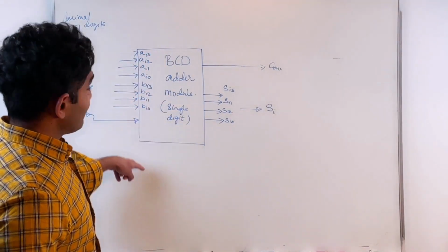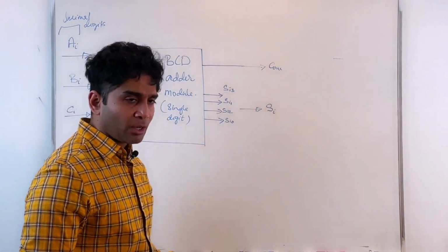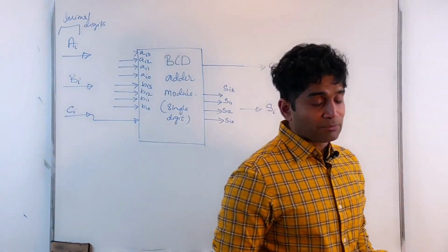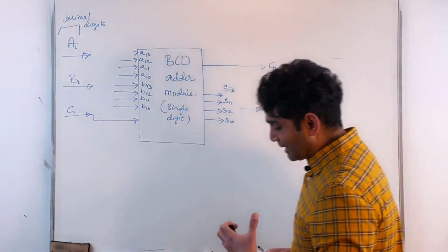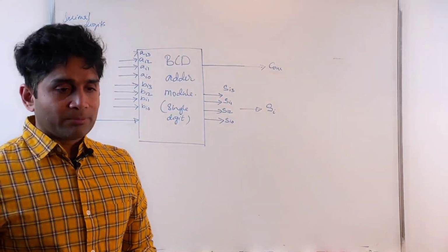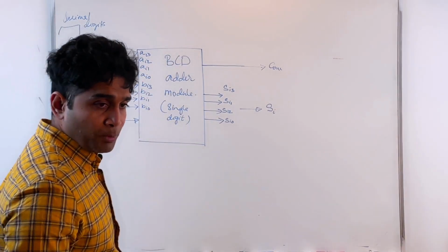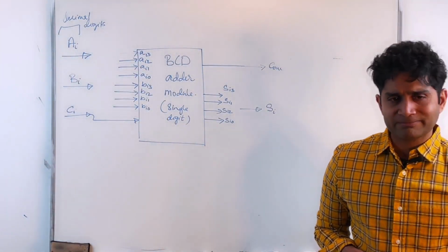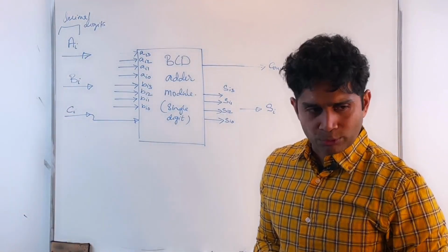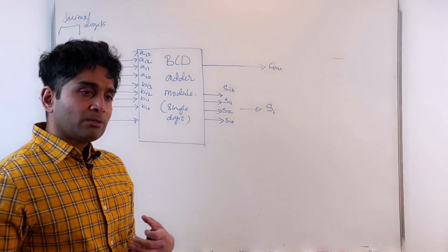I already see that I have 9 inputs, and I don't really worry about the outputs, but I have 9 inputs. So if I were to design it with fundamental gates, that's going to be complicated, right? Again, I'm looking at a 2 power 9 cell K map, and that's not a very practical approach. Okay. But how about doing it in alternate ways?